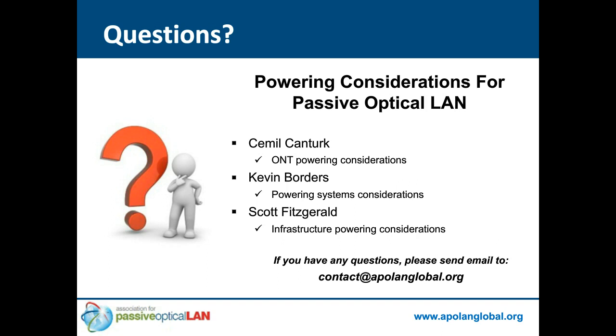That could happen, but typically what you have when you centralize the power is you have multiple layers of redundancy. So your rectifiers will usually be deployed with an N+1 redundant arrangement, which means if one of the rectifiers fails, you still have enough power coming out of the rectifier bank. The second thing is that your batteries are typically deployed with multiple battery strings.